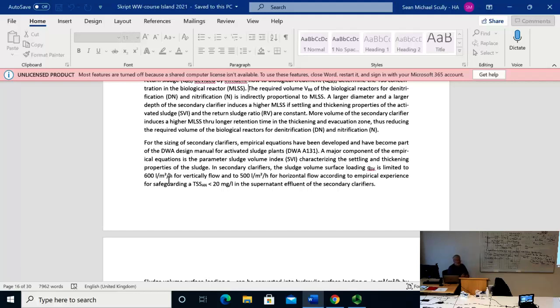In a large city, some people shower later, some earlier, so you get a pretty even inflow at the wastewater treatment plant. This is different in a small village, because in a small village there's no flow time. It doesn't take longer than an hour from the farthest point for the wastewater to get to the wastewater plant.